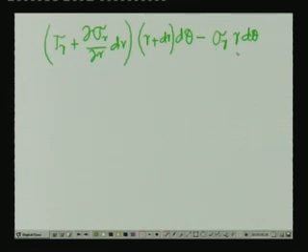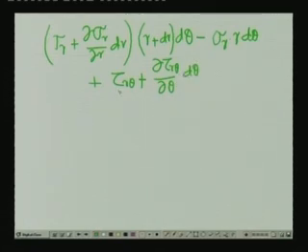So, this is the force. Then the shearing forces which are acting in the theta plane are plus tau r theta plus del tau r theta del theta acting over the length d theta, and the area is dr, minus tau r theta over the area dr times 1.